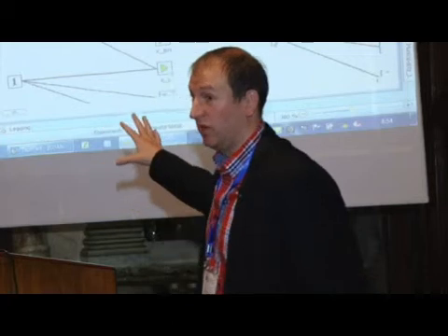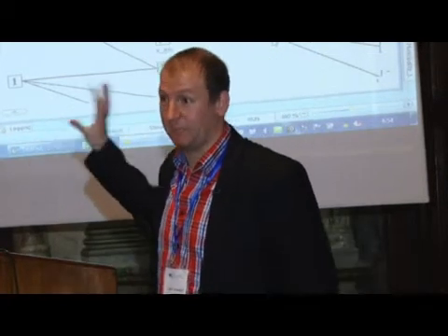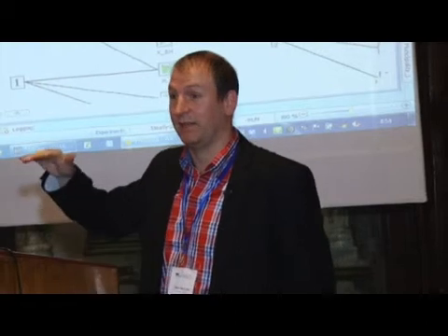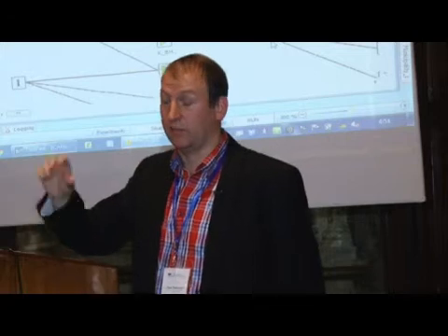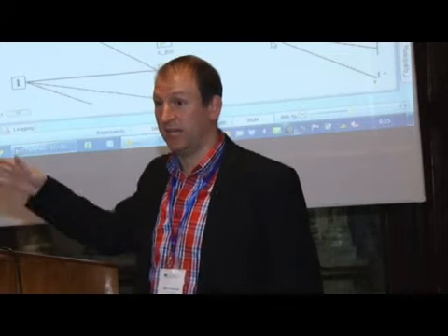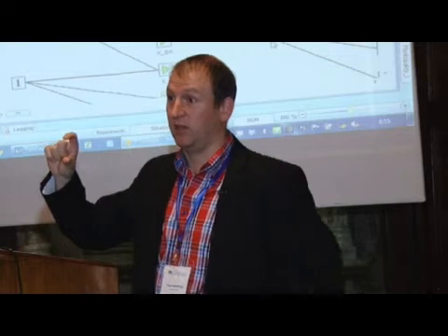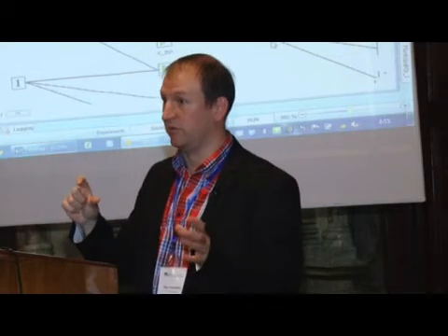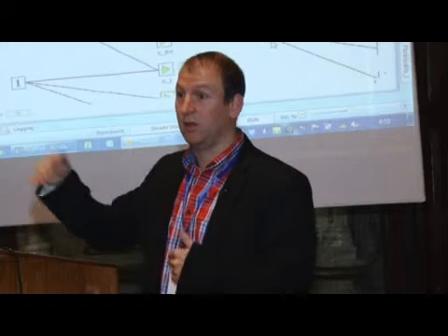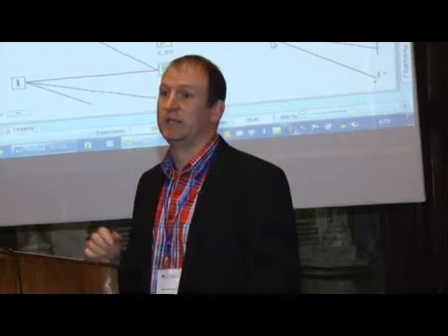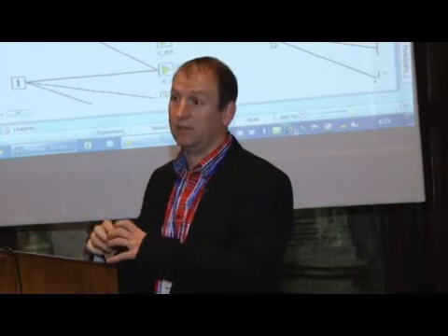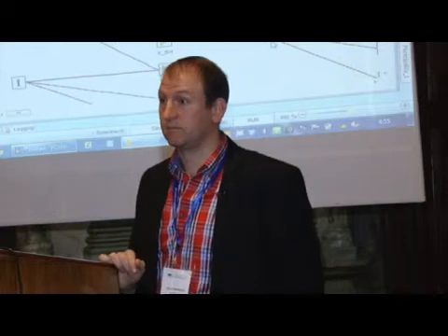Maybe we can take a second to take some questions. Another aspect to address for this kind of software: these are dynamic simulators. So far, I'm only showing the steady state simulations. But after the break, I'm going to show some dynamic simulations, and then you can really use this where you cannot use the design software for calculating peak demand, looking at effects of storm events on your clarifiers and so on, which gives you more detail in the design of the plants.